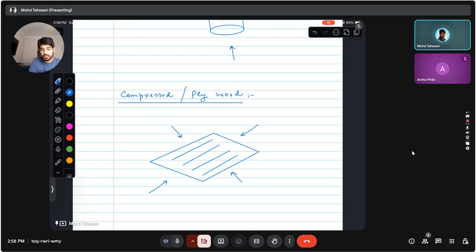right? And sometimes this is intentional. We want to design materials which are anisotropic based on our needs, and this whole area of composites offers us a nice way of doing it. So, for example, one layer of composite can be in this direction, and the next set of fibers we can lay at some angle, let's say a 30-degree angle to this, right?